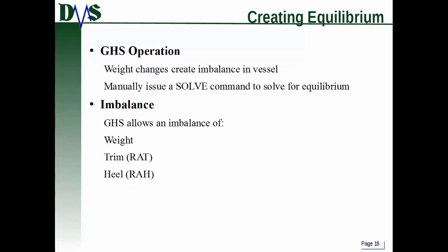Now, for anybody that's used some of the more advanced features of GHS, like Load Editor, in that case, it does have a few auto-solve features, but when you're talking command line only, it does not automatically solve. And it's better for you to assume that it doesn't automatically solve, because there's no harm in issuing extra manual solve commands. And if you really want to be a powered GHS user, you've got to get that in your head so you're comfortable working from the command line.